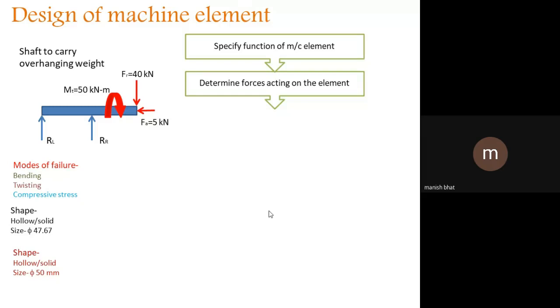If you fail to analyze this particular force, what will happen? The shaft you have designed only for radial and axial force will fail when it is rotating. Are you understanding the fact? If I estimate just radial and axial force, and don't estimate that torque, what will happen when the shaft rotates?